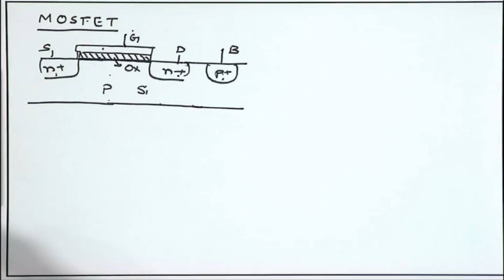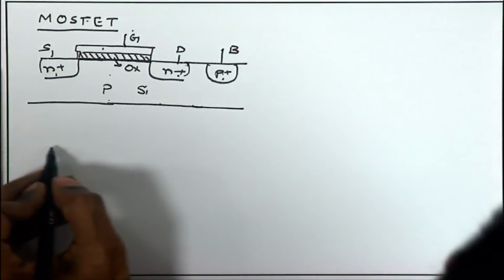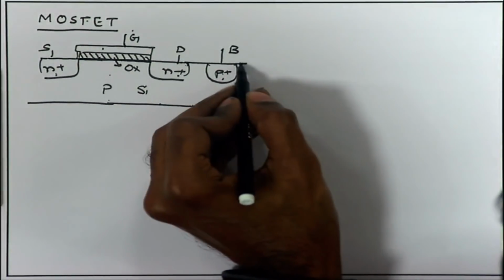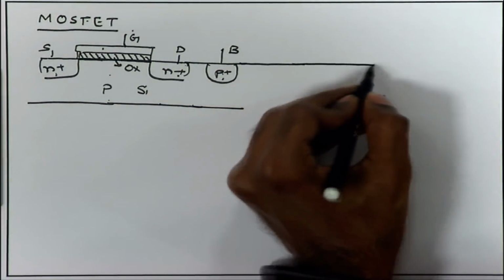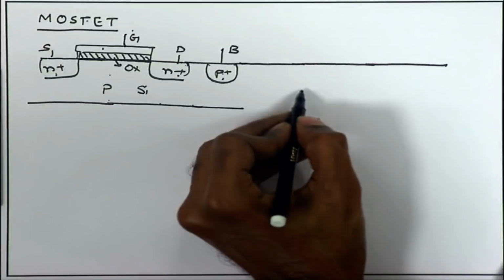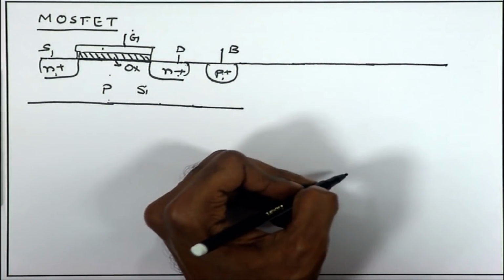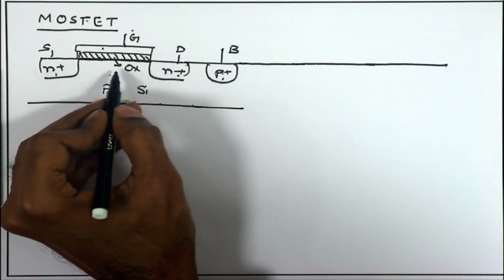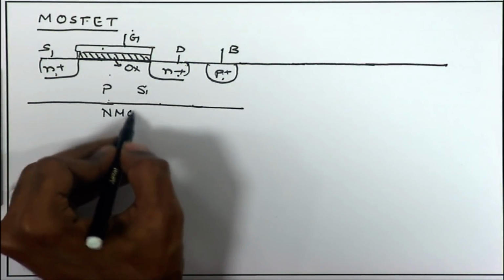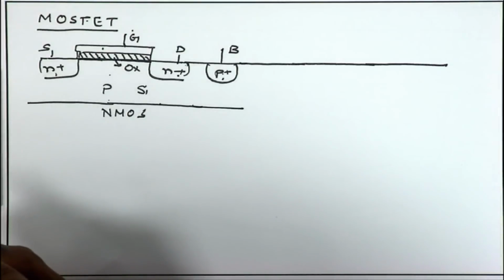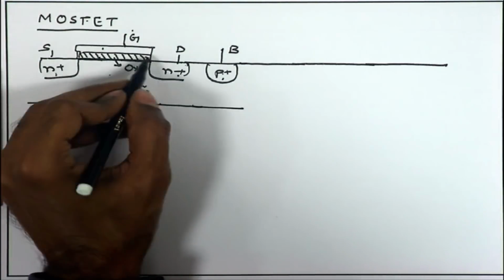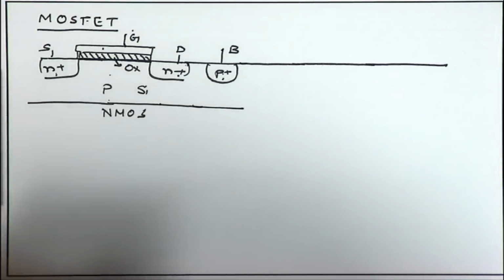For an N well technology, we know what the condition is. We have this entire silicon wafer doped P type. So, this entire silicon wafer to begin with is doped P type, and the NMOS transistors are directly fabricated on top of that silicon wafer. You have the N plus regions and the gate forming the NMOS transistor directly on the P type substrate.